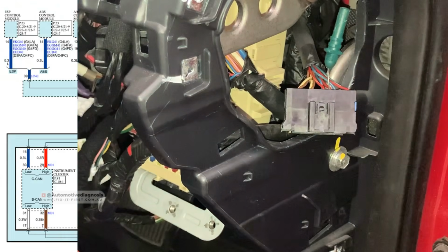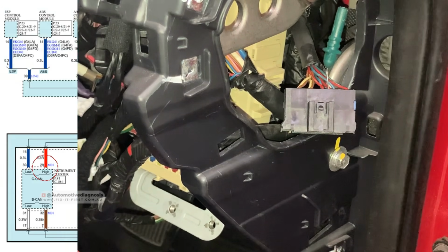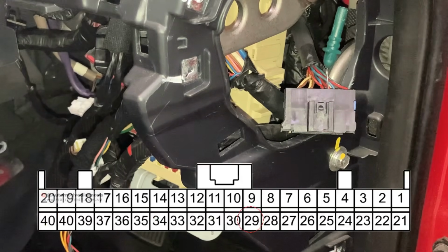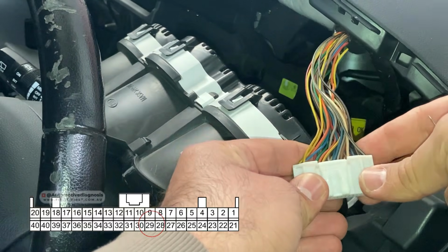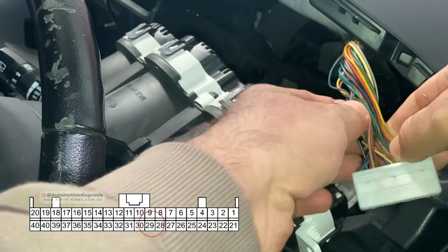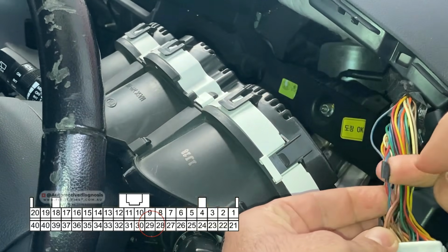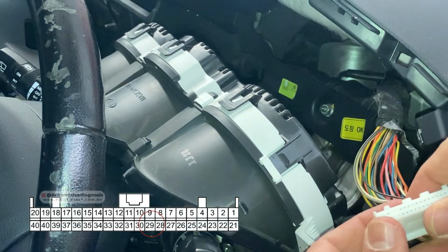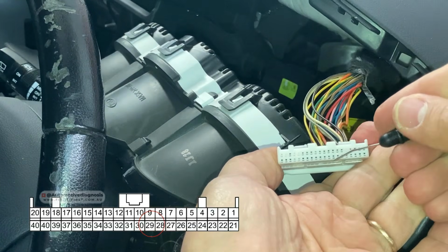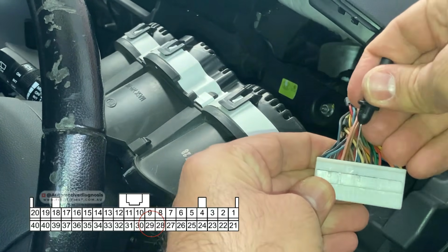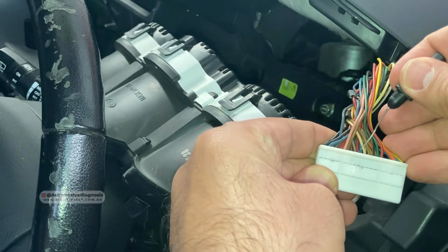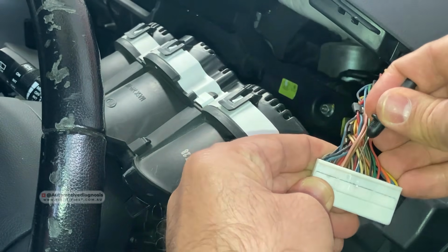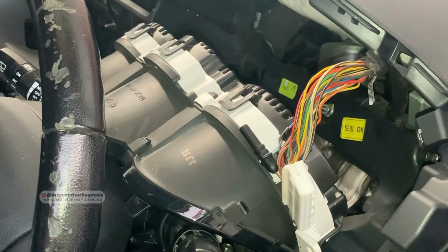And the other end of this CAN high is connected to the instrument cluster, as you see on pin number 29. So you see the pin number 29 on the instrument cluster connector too. So here is the instrument cluster connector. If you look at here, these two wires which are twisted, they are CAN high and CAN low. So we are looking for pin number 29. If you look at the connector like this, based on what we have there, it's just right here. And if you look at the back, this is the CAN high, this red one. You see the red and blue, they are next to each other. The blue one is CAN low and the red one is CAN high. I'm going to insert the probe right there. And now we can go for testing the wiring.